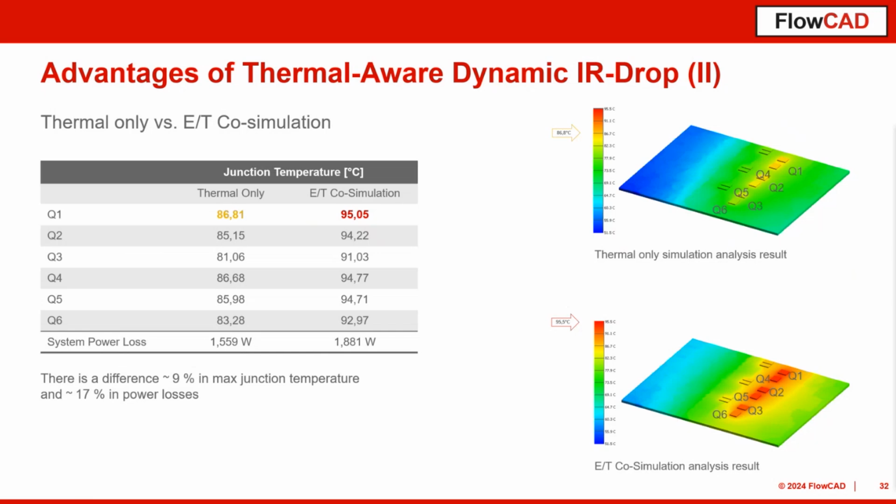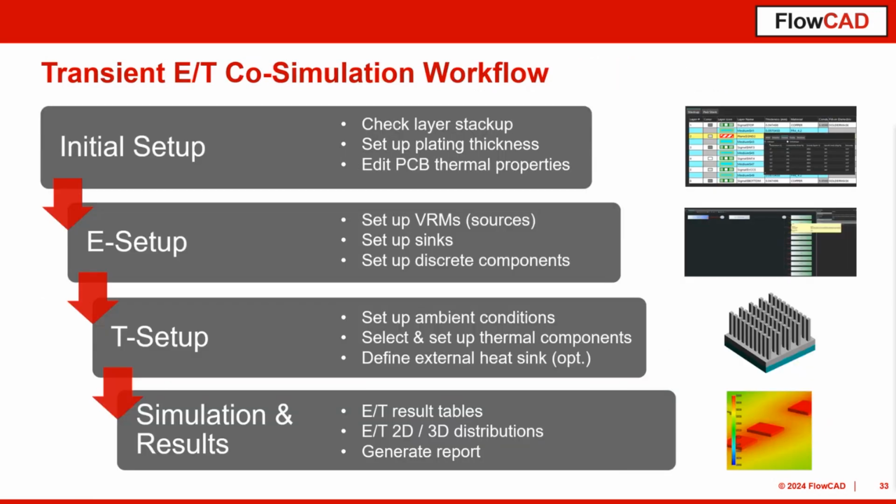I think that is very interesting to see now also for you how that works in a live demo. In principle, we have to start again with the typical initial setup, as we have seen it for the IR drop analysis, create our power distribution networks with electrical analysis for sources and sinks. And the thermal setup is quite straightforward, similar to the electrical setup. So you need to set your ambient conditions. That means the temperature, and maybe also you can add some airflow into the design.